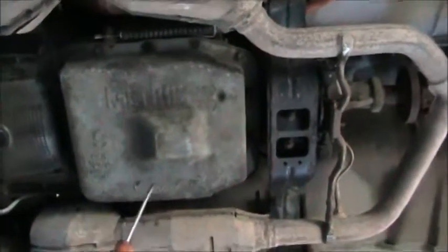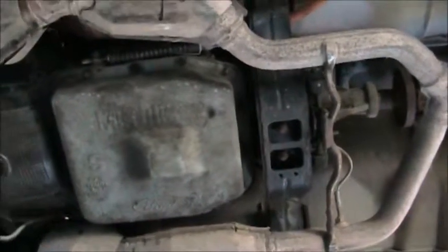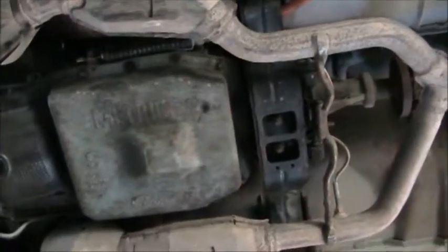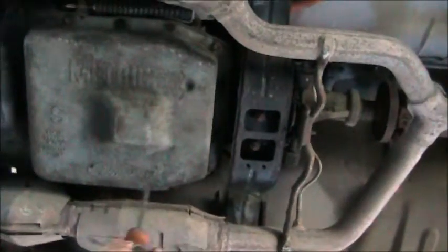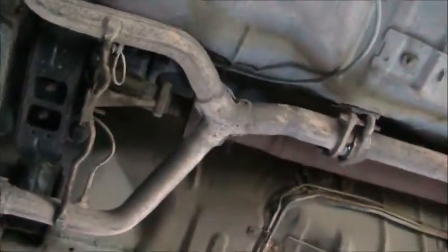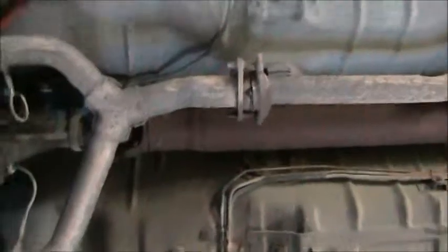All those work together to give you all the different gear ratios, being 1, 2, 3, and 4 in forward and 1 in reverse, because this is a 3-speed with overdrive automatic transmission and 1 speed in reverse, obviously. That's pretty standard on most cars. A lot of modern transmissions are even 6-speed automatics now.